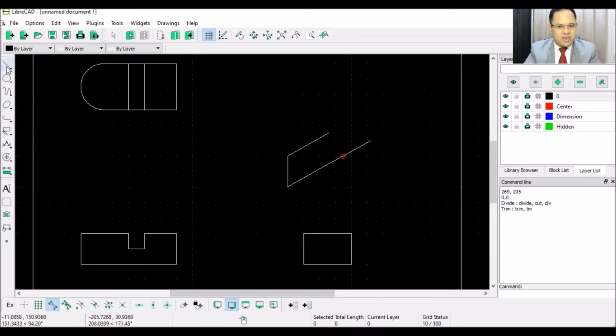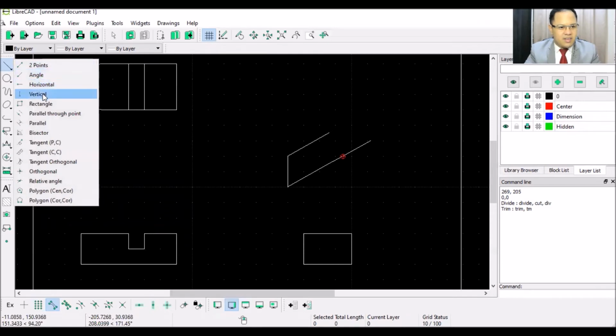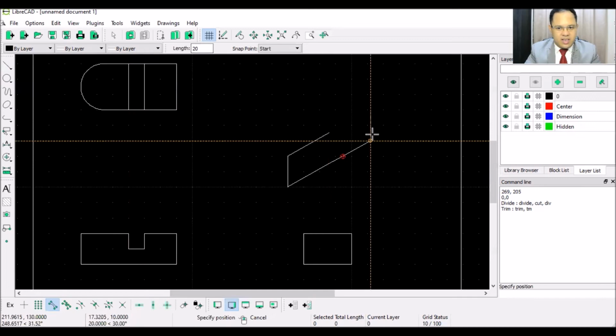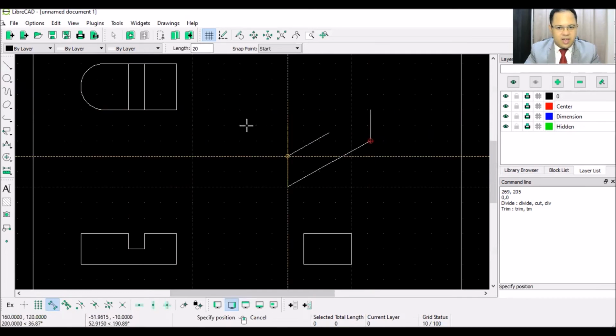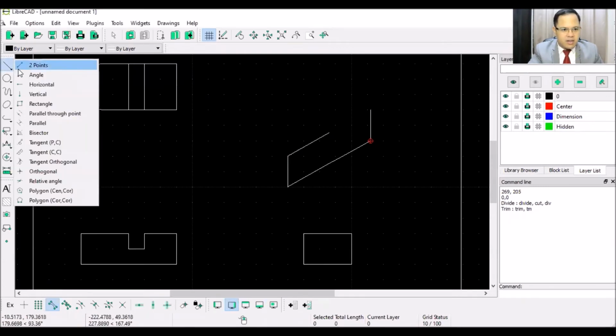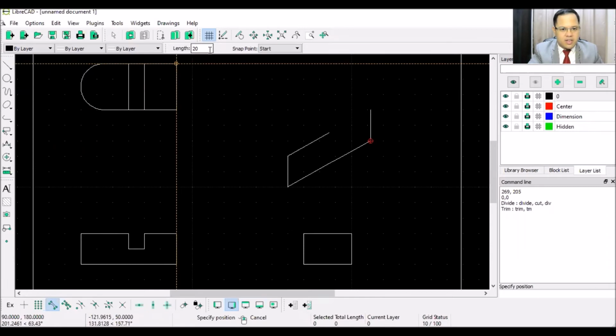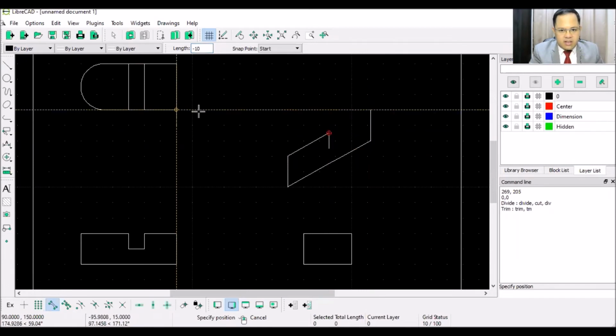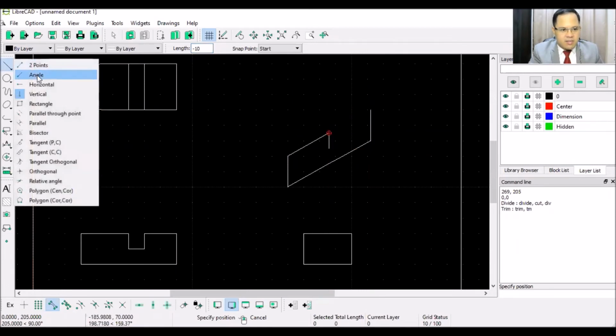And afterwards, I want you to select this line again, then vertical, 20. I have now vertical line. So this time let's try to continue this line by clicking vertical, to make it inverse, I want you to type there -10. So we have now our line there. Then, just the same.